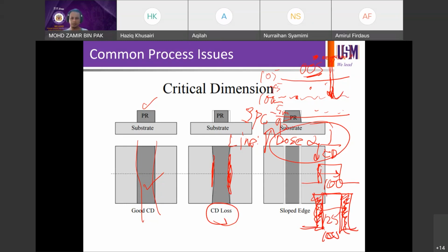So my point here is, when you do troubleshooting, in any case, not necessarily working in a fab, when you work as an engineer or technical person in your career later on, first, before you decide on anything, define the problem clearly. Understand the problem clearly. Sketch the problem, draw the SPC chart, write the relationship, draw the cross section. After you see the SPC chart and the relationship here, then you sketch the CD problem. I was supposed to get this, but I'm not getting this, instead I'm getting this. By these sketches, at least, okay, this is the actual problem. So this is defining the problem to make sure that you are clearer.